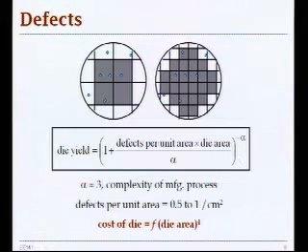And the die yield had to do with mechanical defects introduced in the process of manufacturing your design, and it can be calculated using this exponential formula, where this exponent was related to complexity of manufacturing process. And in today's processes, this alpha term was typically around 3. So having that in mind, in previous formula, we concluded that the cost of a die is a function of the 4th power of the die area. So it was very expensive in terms of having defects.